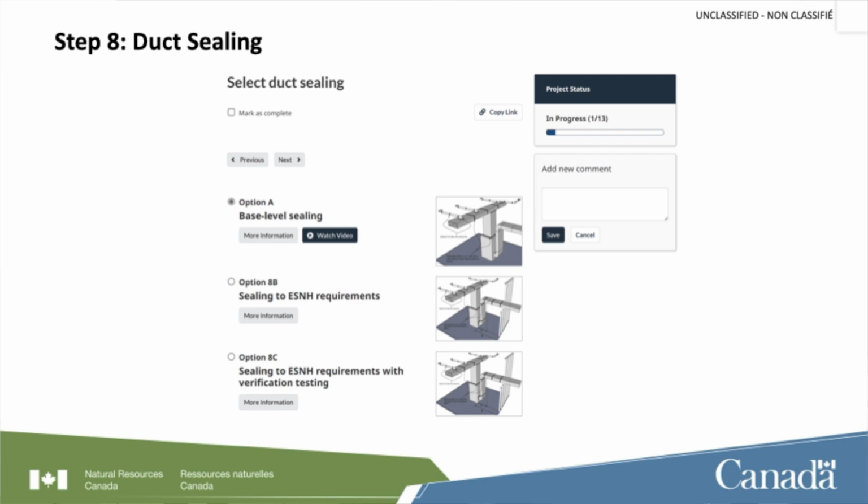The last option is sealing to the Energy Star requirements with verification testing, and that's why I brought this little guy over here. This is what we call a duct blaster. Feel free to have a look at it. It's basically an air pressurization test for your ducting. So if you're doing EnerGuide, you're probably familiar with blower door tests, which are depressurization. In this case, we are sealing up all the ducts, sealing up the cold air returns, and we are pressurizing the systems to measure the amount of air leakage.